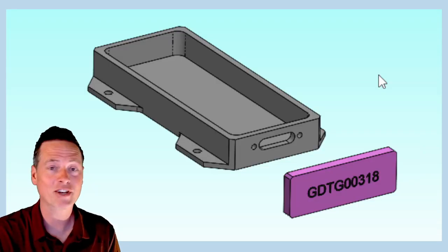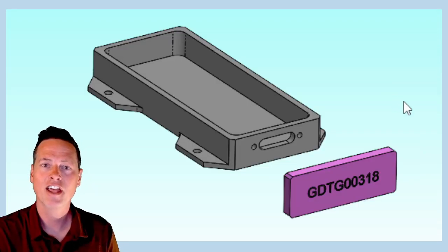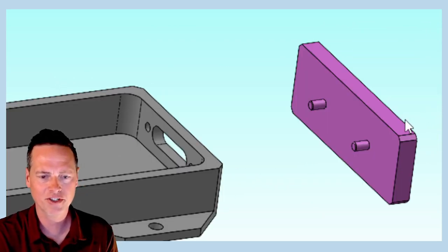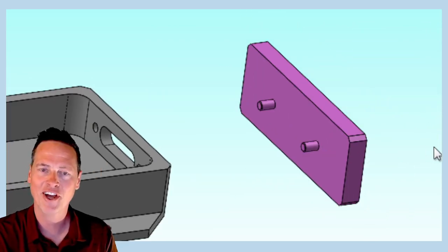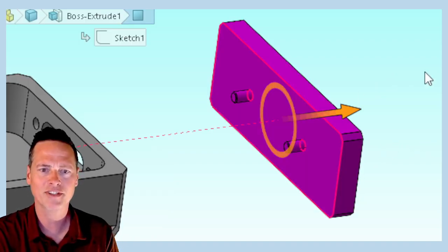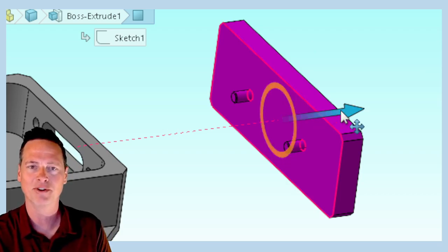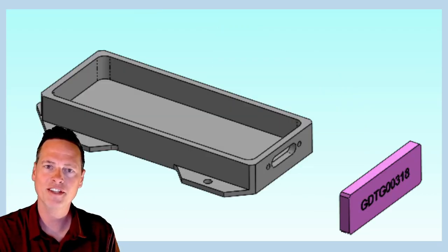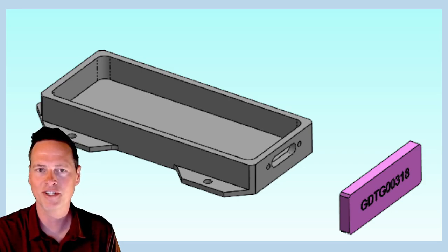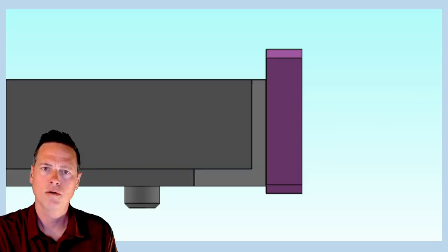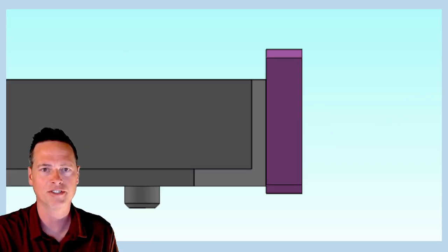Okay, for this inspection, gone is the fixture, and it's been replaced by this cute little gauge. It has two cylindrical bosses. They're exactly 120 thousandths in diameter, perfectly spaced, perfectly perpendicular to our datum C simulator, which is this flat surface. And this one just has to fit into these holes until the datum C feature makes solid contact against the datum C simulator. Well, what happens when there's some orientation deviation on the datum C surface?